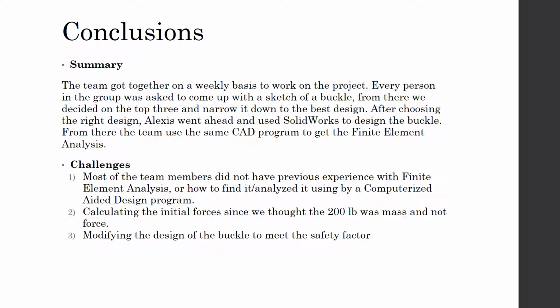Some of the challenges we had were just learning some of the software and calculations to go with it. Initially, we made a mistake calculating the force, which gave us a much larger force, which did not seem reasonable. So we looked into it and realized that we were doing something wrong calculating the force of the man. Our force was way too big because we were not taking into account that the weight already takes gravity into account. So once we figured that out, it let us make our design much smaller and more efficient, and we were able to modify it from there to meet the factors of safety.